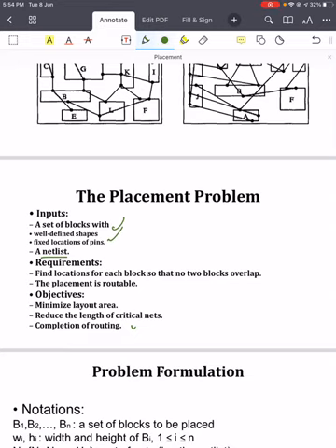From the routing stage, again you have to go to the placement stage, adjust your block positions, and based on that again perform the routing. So your overall design cycle time will increase. That's why this placement step is important. Okay, I hope you have understood.